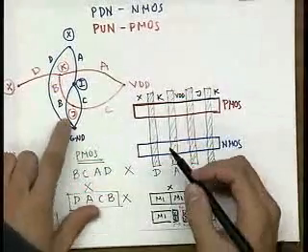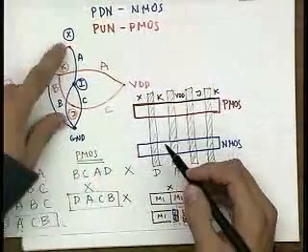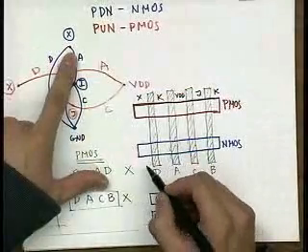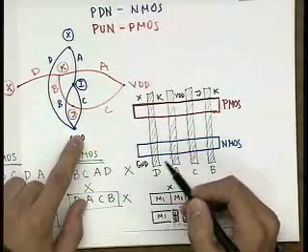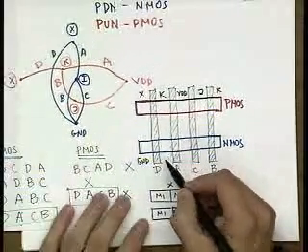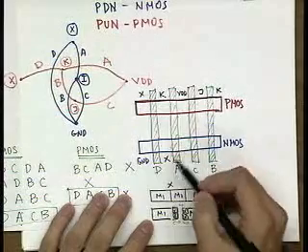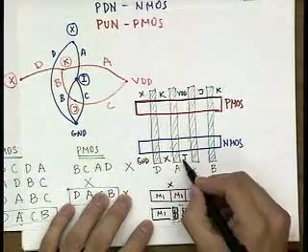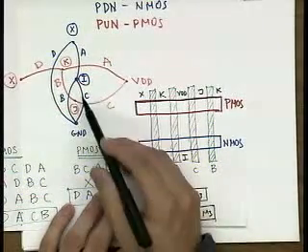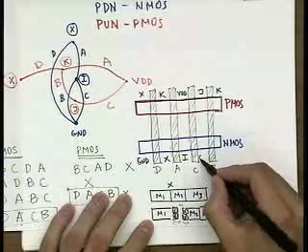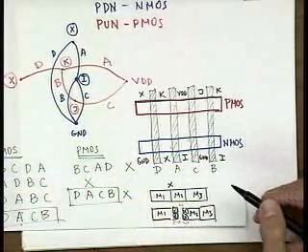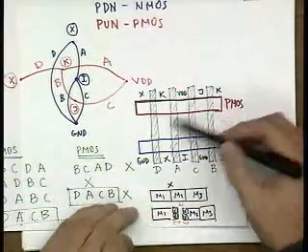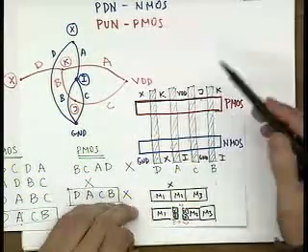So for the NMOS, you go a similar way. You basically start with D. So over here, you have ground. Then you go up between D and A, you have X. Then between A and C, you have I. Between C and B, you have ground. And then you have I again. So all you need to do now is basically connect all these source and drain areas.